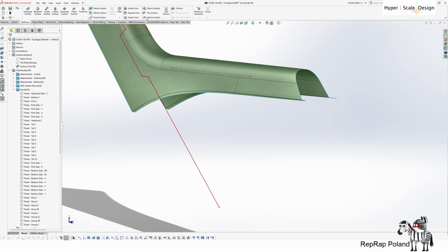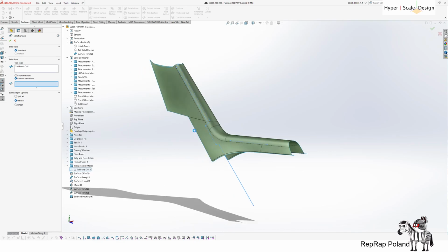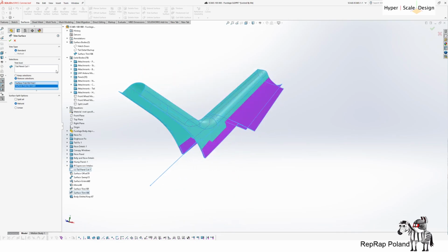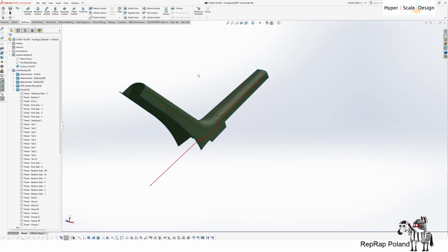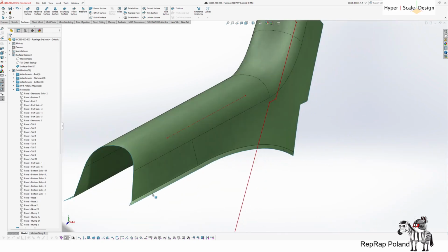And I'm gonna use the sketch to trim the back side of the panel here. And hooray! Huzzah! I've got a surface that's been trimmed perfectly with this offset being the exact 24 millimeters across the whole crease.